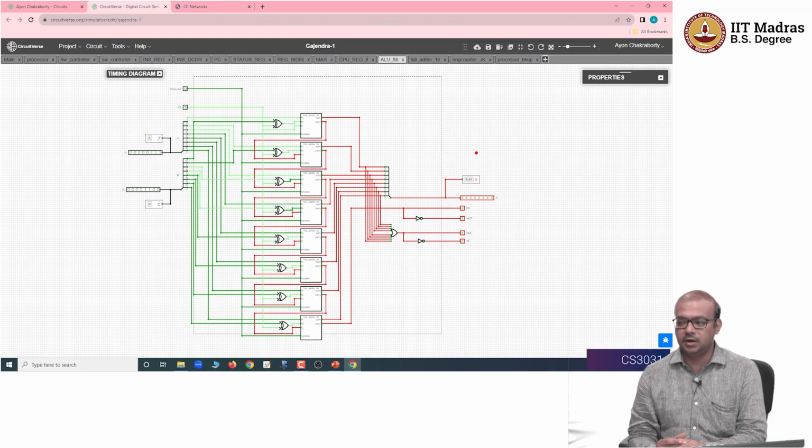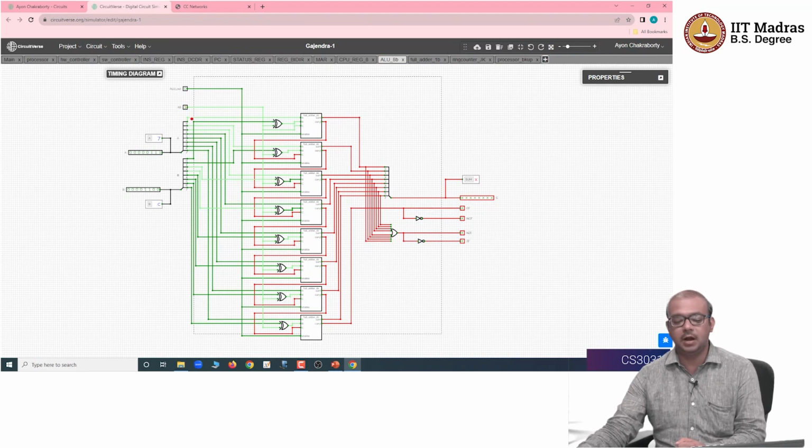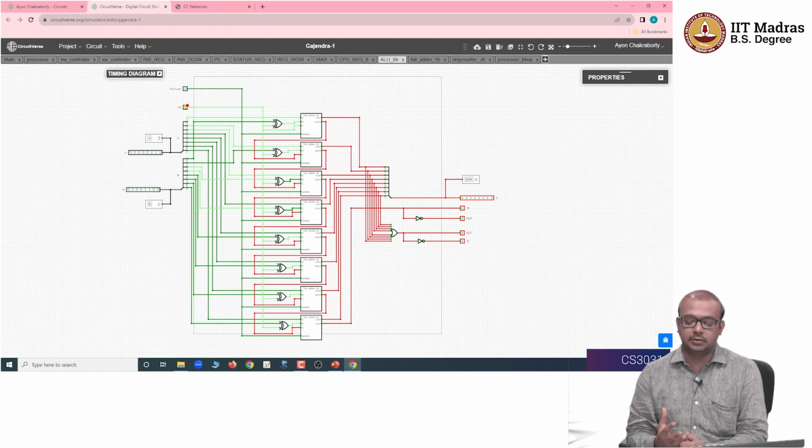And then we also looked into the ALU now, so you know kind of how subtraction works. So we are going to restrict ourselves to this. If you had logical operations on top of this, suppose you had AND and NOT, as we discussed, right? So in that case, what will happen is this ALU select, right, is going to be 2 bits, not a single bit. And this is going to go to a decoder. Okay, so this decoder is going to see if it is 0 or 1, assuming that add is 0, 0 and subtraction is 0, 1.